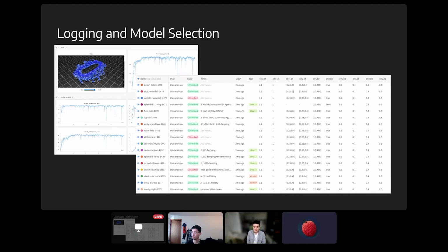I did have this kind of vision where we would train a policy and it would work across all sorts of different frictions, and I think that's the goal with domain randomization. But we realized in practice that is not really the case, and it is known that if you domain randomize your simulation, you just get a really conservative policy that tries to work in all of these domains, but really it's just the worst of all of them. And so you have to be a little bit more specific.